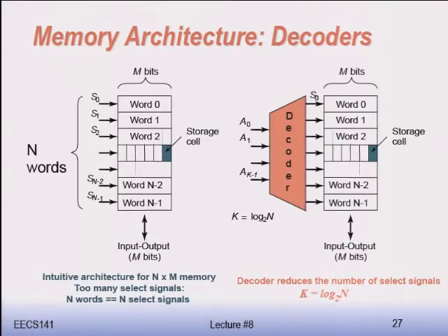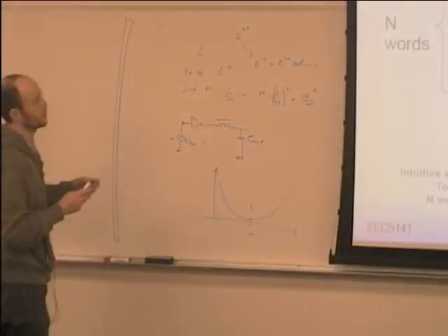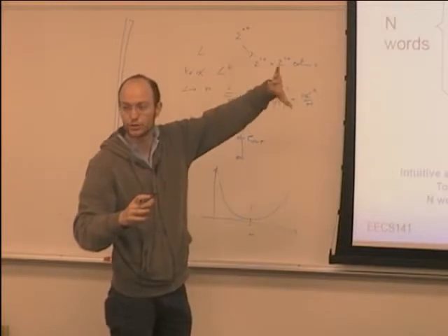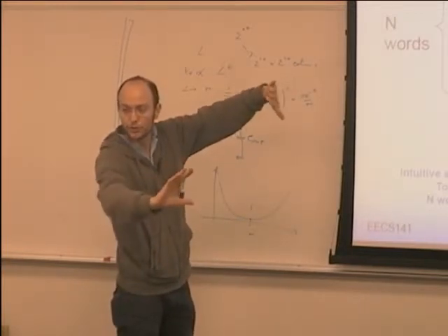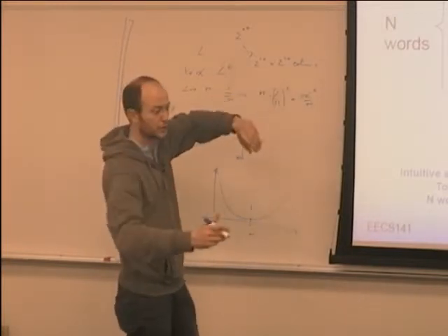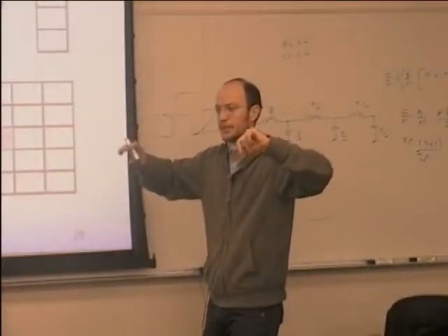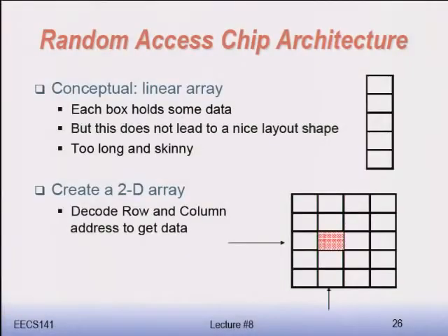Then I want a piece of logic, this decoder. What it does is you put in 10 bits. There is one decoder for the rows and one decoder for the columns, because as I said, the way it works is that these two decoders operate independently. I send a 20-bit word, because to choose between 2 to the 20 cells, you need only 20 bits, right?